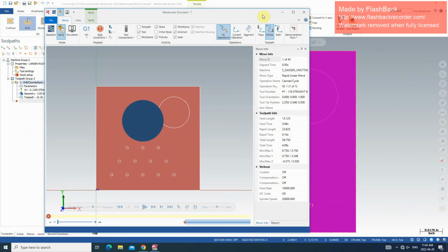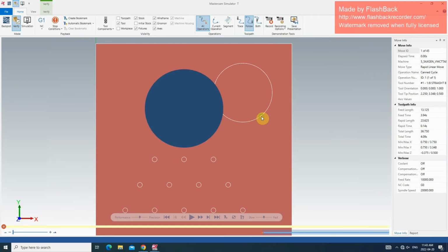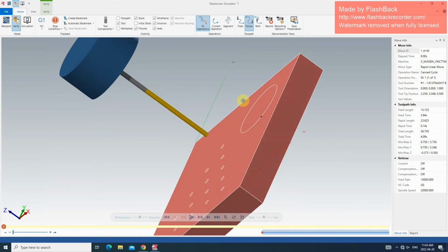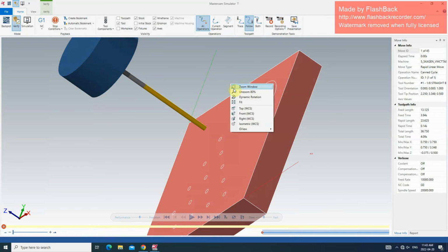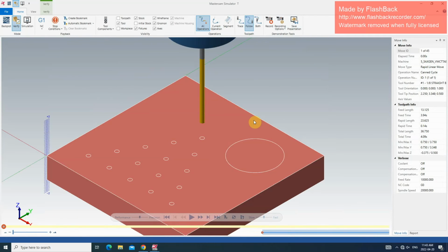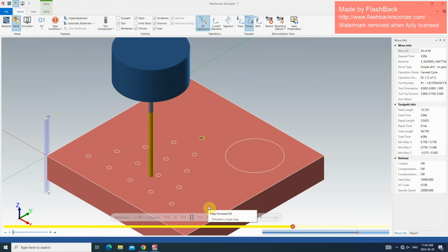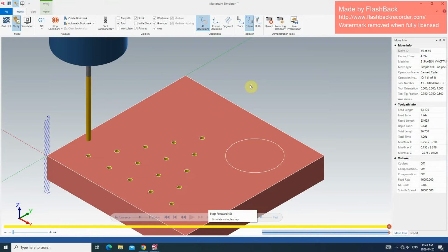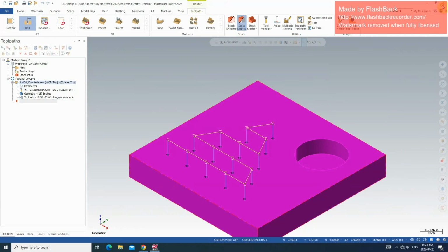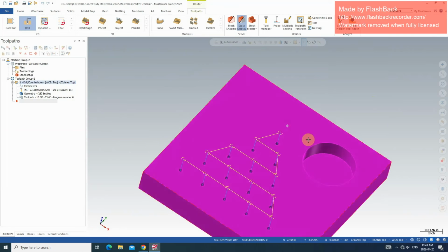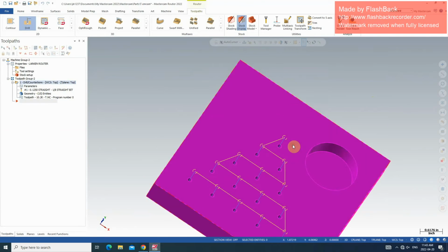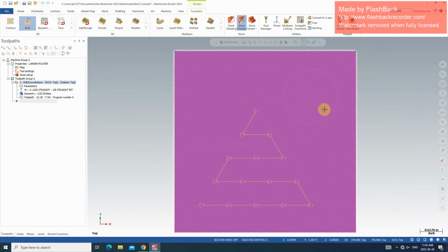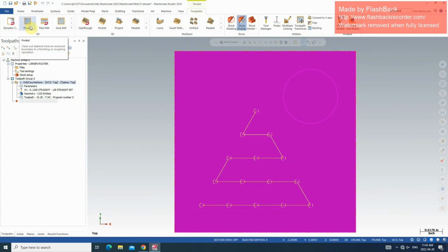This is going to load a visual image of what we just told the drill bit to do. So you can make it an isometric angle and go ahead and adjust the speed and press play. Here you see the drilling pattern that we just established in toolpath. Now we can right click, press top, and it's time to do the toolpath for that top right corner.